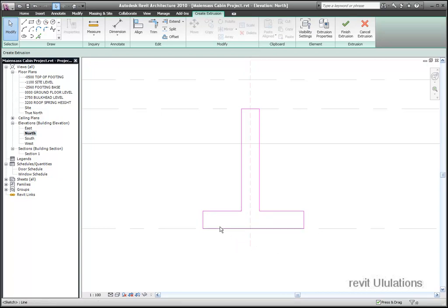And basically the vertical bits, I need to select it first. I don't have that dimension, but I know that from the left edge to the middle is 550, so I can drag that and change the dimension to 550. And again, I'll do the same for this edge here, the right edge. Drag this blue square to the middle, and then change it to 5500. Oh, that was a bit much. 550. Yep, it's 550, isn't it? So there I have my inverted T.